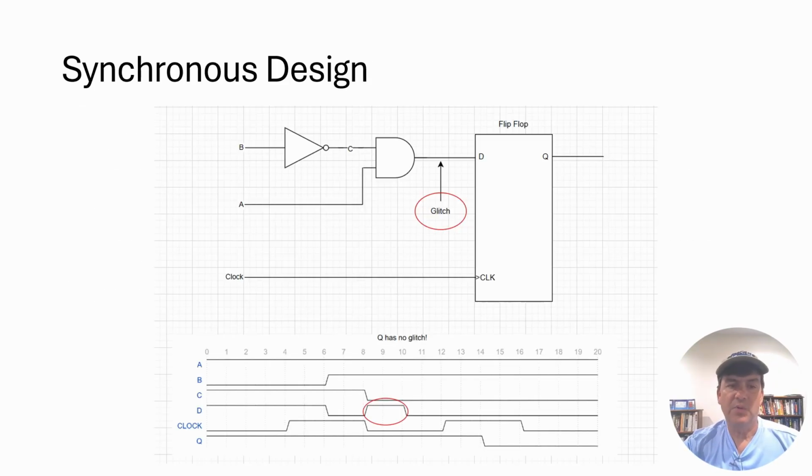Synchronous design solves most glitch-related problems because flip-flops sample signals only on clock edges, after combinatorial logic has settled. Brief glitches inside the logic are ignored as long as they occur between clock edges and timing requirements are met. This prevents unintended state changes, eliminates most race conditions, and ensures predictable, hazard-free operation. The data path in the slide, which is synchronous to the clock, illustrates this principle. However, synchronous design does not eliminate glitches on asynchronous signals or on sensitive inputs such as reset or clock pins, which still require special care.